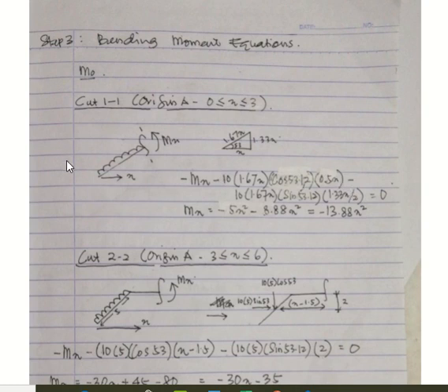Next, the x component: 10 multiplied by 1.67x means UDL multiplied by the length of the UDL, 1.67x. You have one imaginary line for the inclined force. Then to determine the component in x, you multiply with sine 53.13, and you have a force in the x direction here.